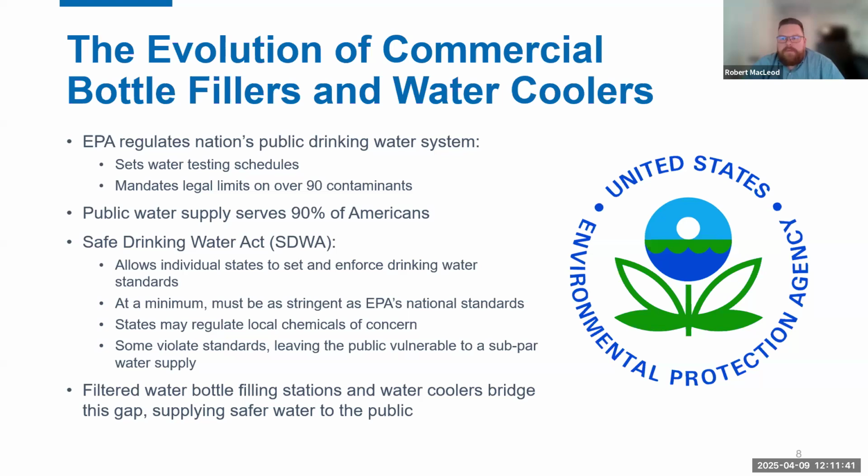The recommendations within ADA are so similar to our local building codes, but there may be nuanced differences, like a rough-in height needing to be a couple of millimeters higher or lower to comply with that province's guideline for rim height, spout height, or knee clearance. So ATS is a great resource for us and for you guys if we ever have to know where your specific project is located, so that we can make sure you have a fully compliant product.